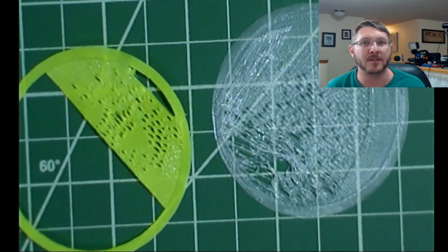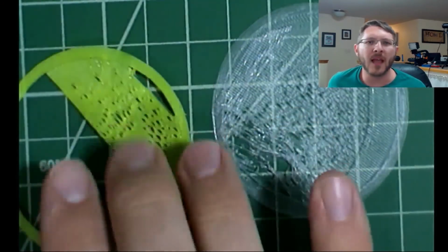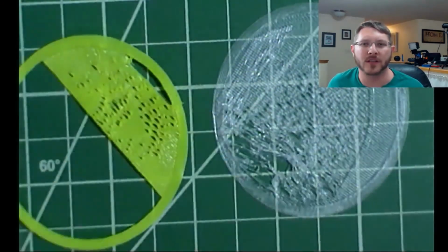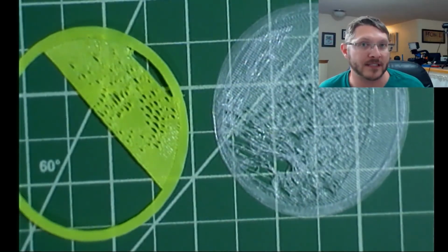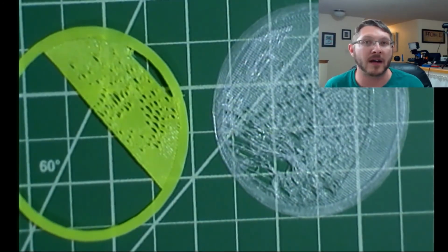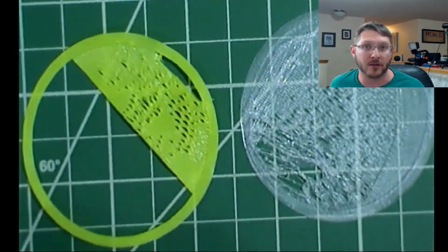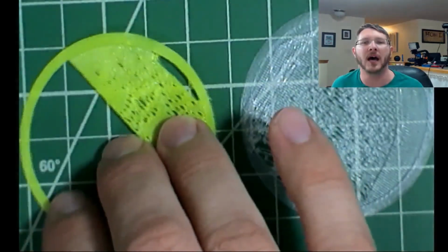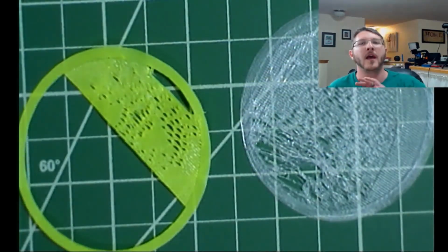I was running it at 55 degrees C for the heated bed, and 50 degrees for subsequent layers after the first layer. So what I did was I upped it all by 5 degrees. So I upped it from 55 to 60 degrees initially for the first layer, and then it would go on up to 55 degrees for the subsequent layers on up. And that perfectly solved the problem. Then it started printing fabulously.